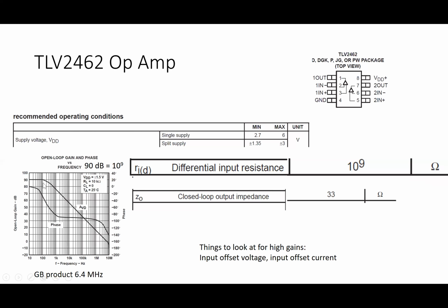Notice something interesting. The manufacturers of this chip have put components on the chip that roll this gain off as the expression for it. It falls on this log-log plot, as this straight line here. And they do this precisely for the reason that I mentioned on the previous slide, which is that if this whole point about finding a stable operating point sounds a little scary to you, it actually is. And at high frequencies where you can get unintended types of feedback, you want the gain to go all the way down to unity, and that's why the manufacturers roll the gain off like this.